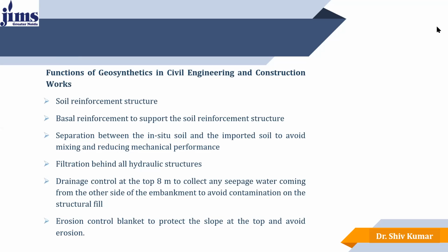Separation between the in situ soil and the imported soil avoids mixing and reducing mechanical performance. Filtration is needed behind all hydraulic structures, and drainage control at the top, at 8 meters, collects any seepage water coming from the other sides of the embankment to avoid contamination of the structure fill. Erosion control I have already mentioned.